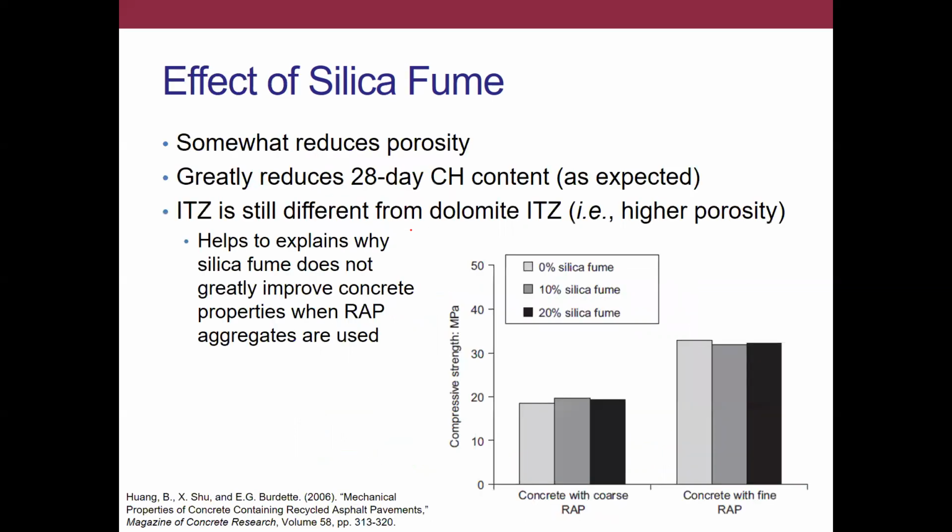And indeed, when we do look at the literature, here's one study from other authors from 2006. You can see that the addition of even up to 20% silica fume did not really affect the compressive strength of concrete. Given the cost of silica fume, it is simply not economical. We don't see sufficient benefit of adding silica fume. So we did investigate this further, and we'll be coming to that in the coming slides with some additional data.